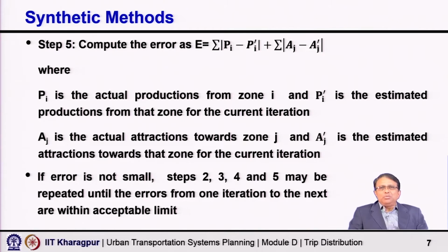Now, why has this error come? The Fij value does not change. Time or cost is given, and correspondingly somebody has calibrated the Fij values. So, in this context-specific given problem, you are not changing the Fij value. Fij will not change, Pi will not change, Aj will not change. So, what will change? What will influence these Tij values? It is only Ki and Kj, the balancing factors.